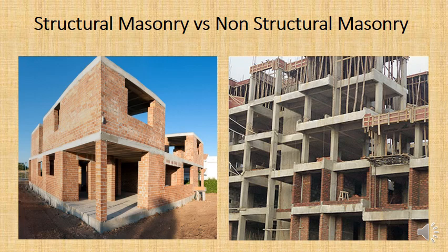What matters is that it's actually low weight, so you're not adding a lot of weight to the building and having to have bigger reinforced concrete columns. So normally structural masonry, we would use that for smaller buildings, usually no more than 2 stories, and we can usually find masonry blocks with enough strength in them.